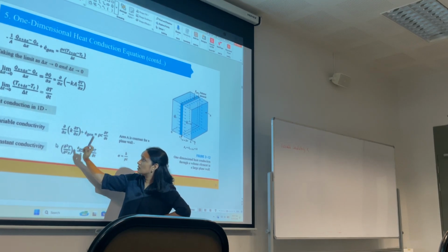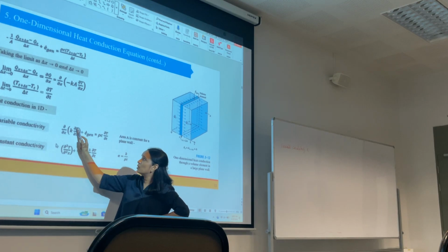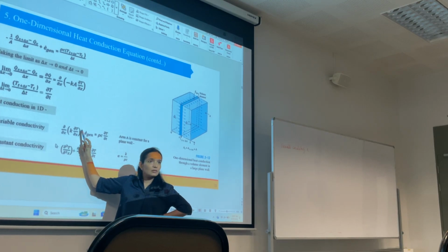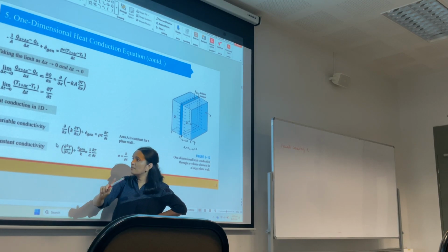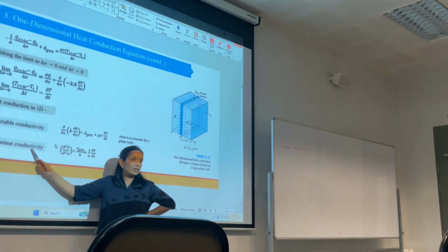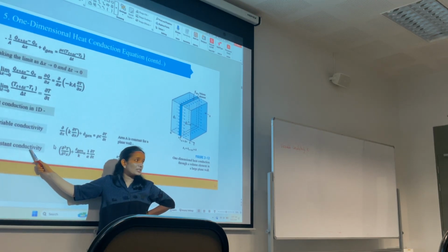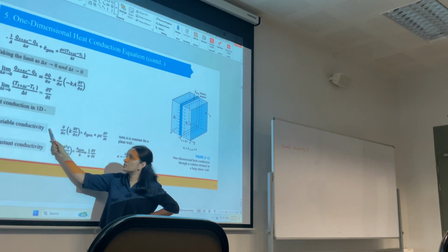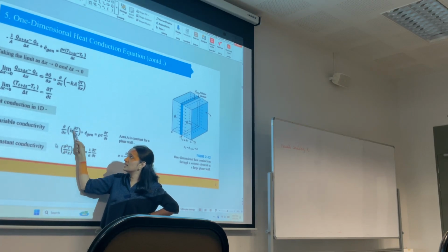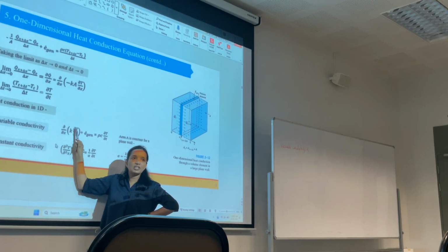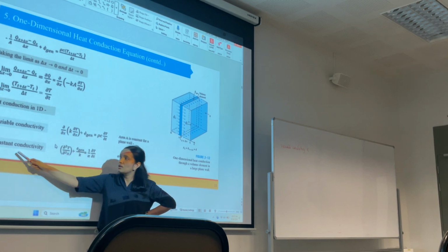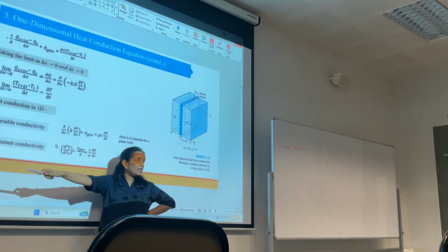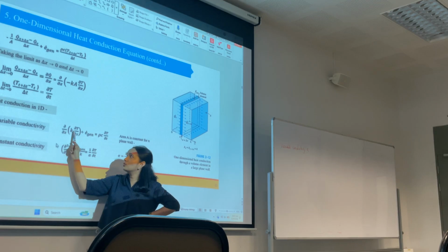What you are trying to do is calculate the capital T, right? Temperature. If your glass has constant conductivity and you want to study heat transfer in your glass, you take this K outside, it's constant. When it's inside, it's variable, it's differentiable, right? When the conductivity of your material or your glass is constant, you take this K outside.